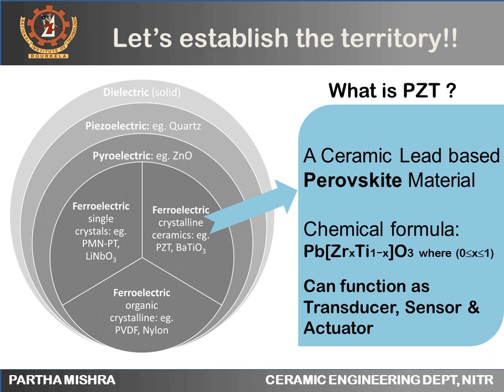But how do crystals such as PZT have such high polarizability? The answer is that these crystals are ferroelectric materials as well. And here's why. What are ferroelectrics? Ferroelectrics are dielectric materials that, although they have disordered dipoles in their domains, when we cool them below a temperature called the Curie temperature, the dipoles orient in a particular common direction, thereby inducing a spontaneous polarization in the crystal structure.